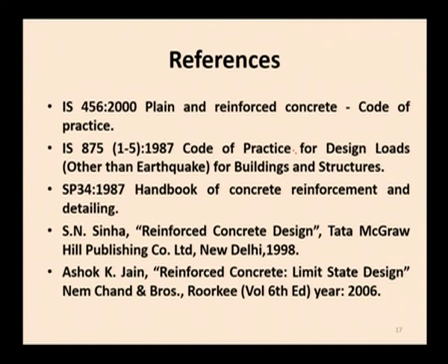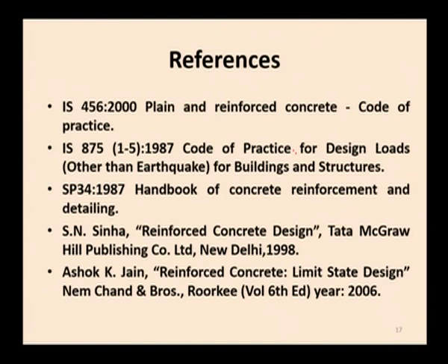In connection with this lecture, the references are IS 456-2000 Plain and Reinforced Concrete Code of Practice, and IS 875-1987 Code of Practice for Design Loads other than earthquake for buildings and structures. Normally we are considering the vertical load acting on the slab. First we must know how to design slabs subjected to vertical load. We can also consider earthquake forces along with the vertical loads. In our syllabus we have only slabs subjected to vertical loads. The vertical loads we are considering here are dead load and live load.